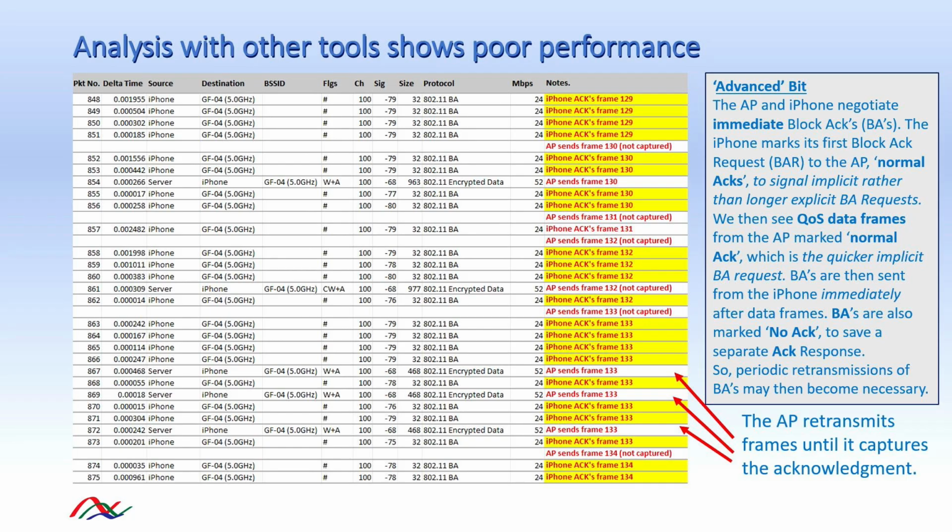Now, just a note on the power levels seen here. Measurements are usually taken near to the client, but in this case they were measured at the starting point, so the signals are weaker and some of the AP message frames couldn't be decoded. They're missing from the capture and they've been noted manually because we know from the other frames that they're there. If we look at the timestamps around the acknowledgement of message frame 131, we see there are some big gaps, so it's likely there are more lost frames and that the problem is worse.